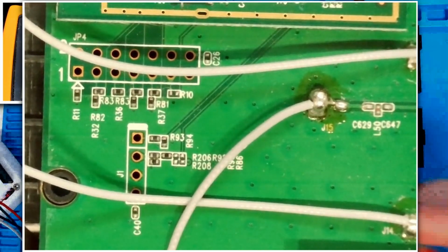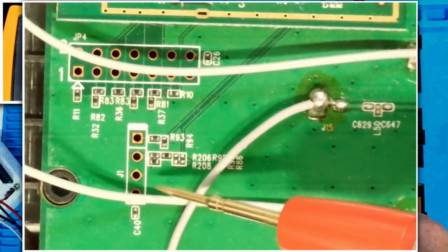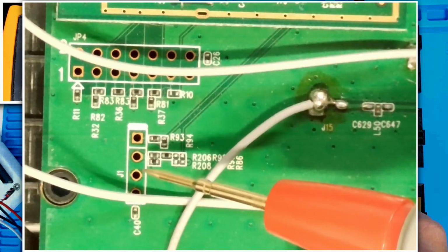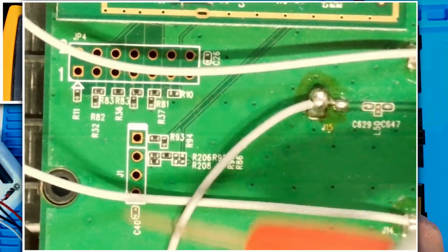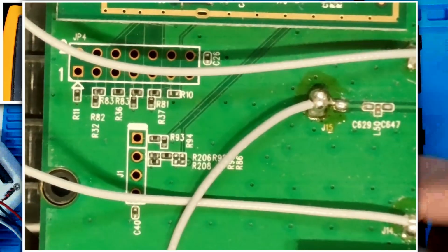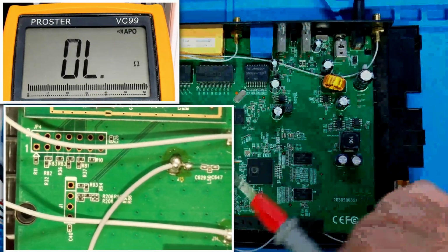And another thing you can look for here is you can see that around pin 3, it has 4 different connections from that pad out to this ground pour around it. And that's for thermal relief, and it's another good indicator that it's a ground signal, but it's always good to check with a multimeter.